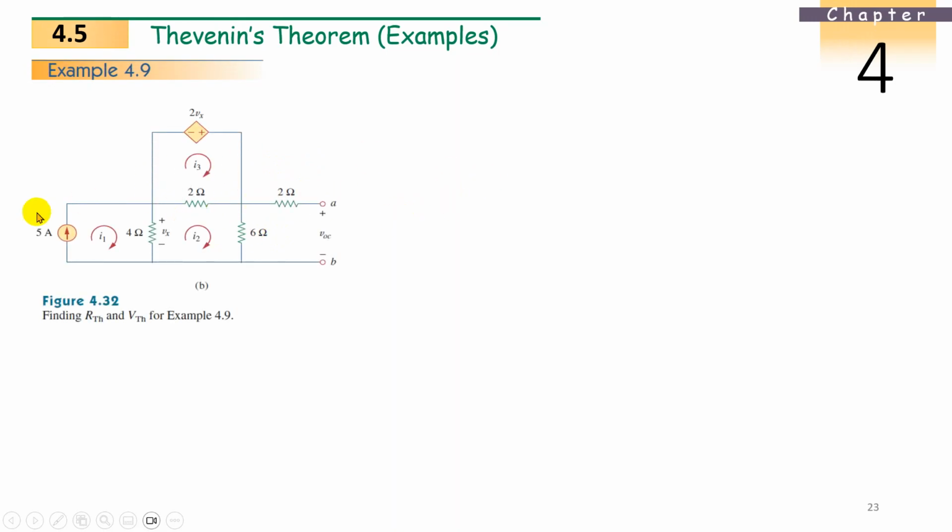So for V Thevenin's, same loop. We have to check with considering all the source currents and everything. Source current should be as it is. The dependent sources should be as it is. Everything should be as it is. Then we have to find the V Thevenin's between terminal A and B. So what is it between terminal A and B? VOC is equal to V Thevenin's.